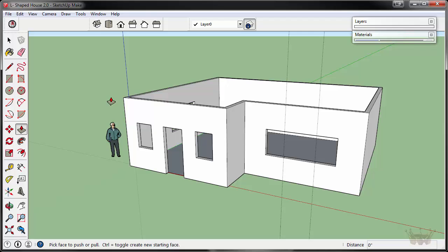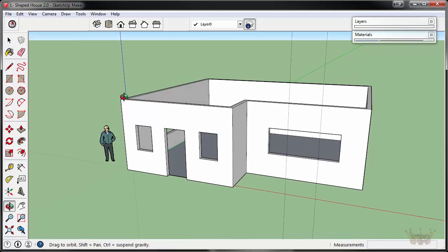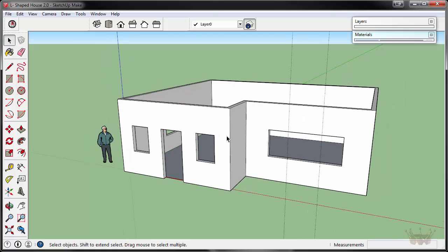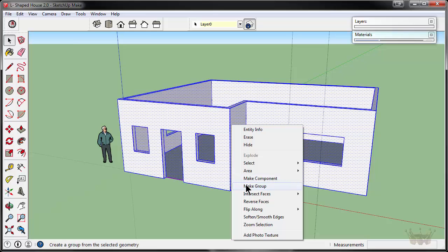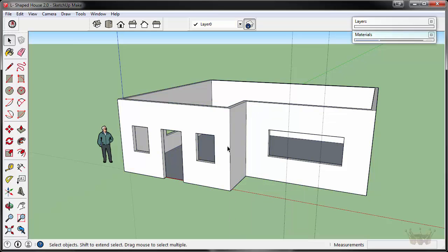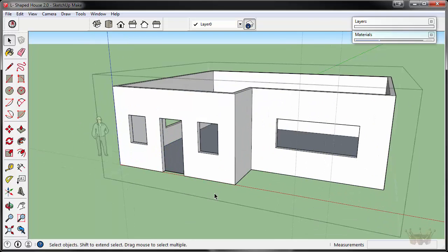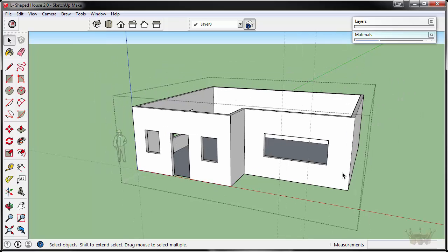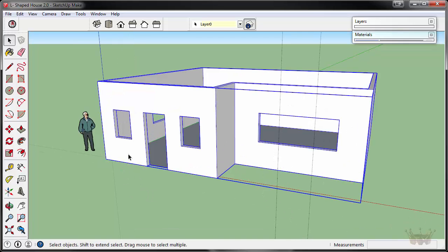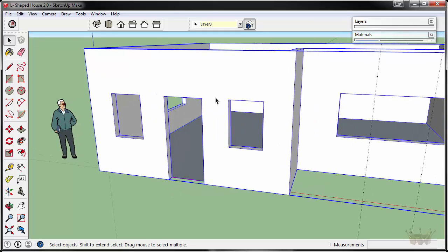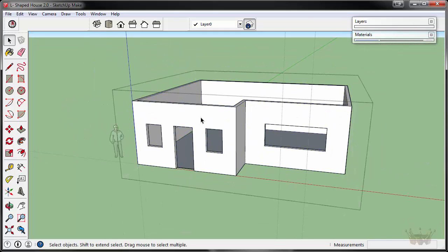However, these walls are set up very specifically for what we want to do. So instead of leaving them unlocked, I'm going to triple click, then right click, and make this entire outer wall section one group, which can no longer be changed unless you double click and go into edit mode. Remember, edit mode will have the lines around the outside and it will allow you to change things. This will be important later on down the road, as we will be making changes to the wall after we have grouped it together. Alright, we're going to start by drawing a door on top of the group. Make sure you're not in the group in edit mode.